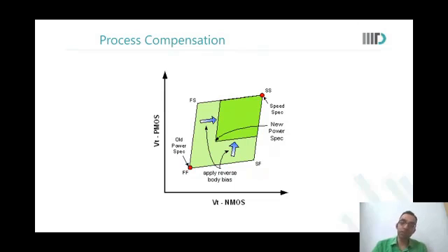Similarly, on the side of reverse body bias, there would be constraints on how much reverse body bias you can put. Again, because otherwise band-to-band tunneling will kind of run off. There will be lots of current that will flow from the source to the substrate or drain to the substrate. So you cannot really do a lot of body bias. So very good and very interesting observation.